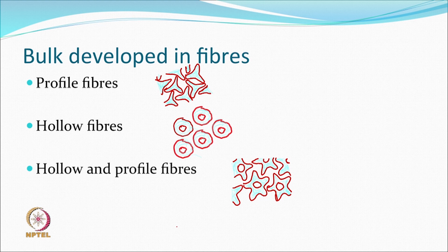There is no stretch here, but you will still be able to see that the same density of a material, same GSM of fabric will appear bulkier, just because you have introduced a different cross sectional area. The cross section could be whatever, trilobal, pentalobal, hexalobal, octalobal, and all of them will keep changing the whole bulk process.